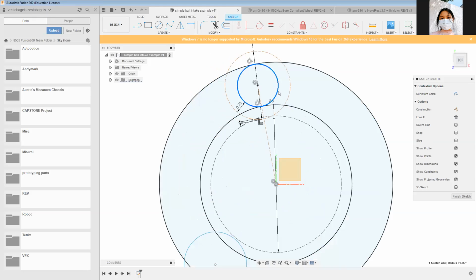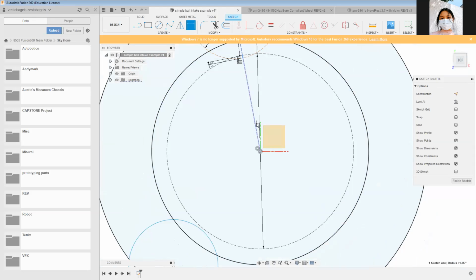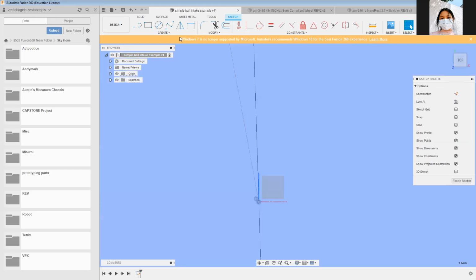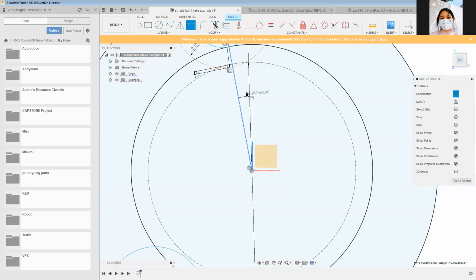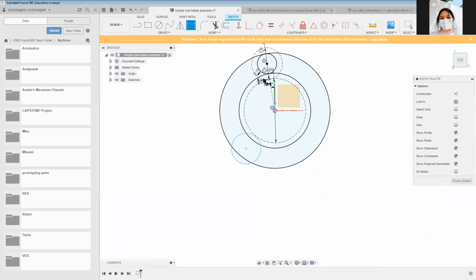Like, so the ball won't come out, so I'm just going to guess a random number that we can iterate later if we make this. I press D for dimension. I want to dimension against this line. I hold down the left click button and I can select this line, and select these 2 lines and it automatically chooses to do an angle. I'm just going to say this is 10 degrees. And that's a good starting amount.